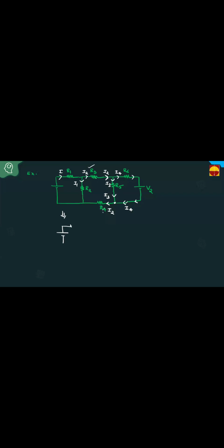This is the voltage. This is R1 and this is R2. And you have to write that the same current is flowing now. What is the current in R3? I2. What is the current in R4? I2. That is, R3 and R4 are in series because of the same connection. You write this R3 and R4 in series. Just simplify the circuit like this.